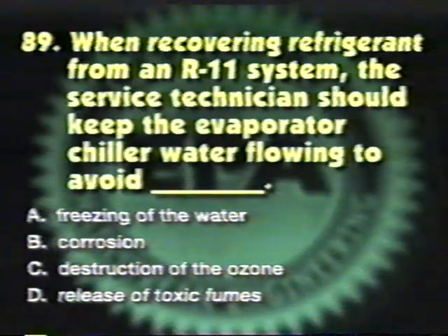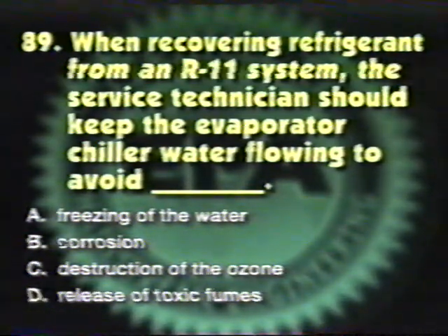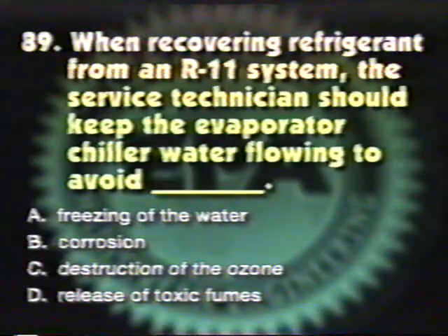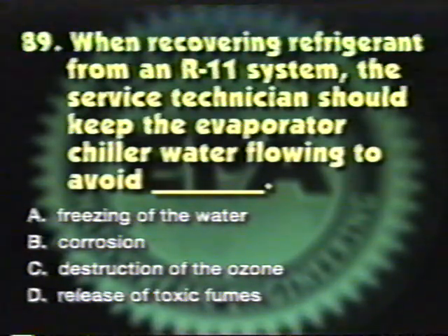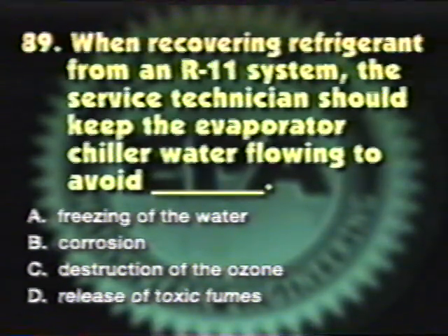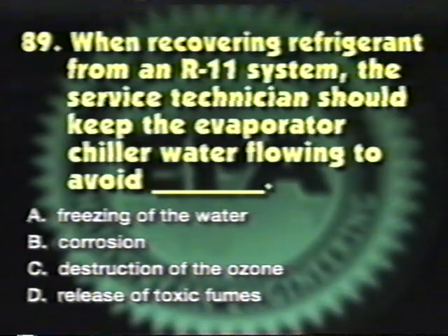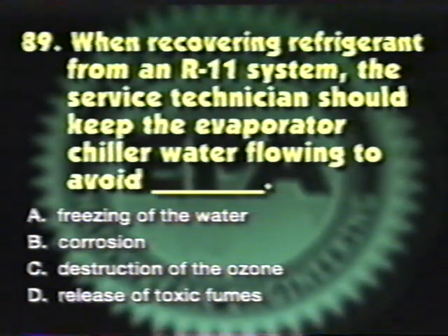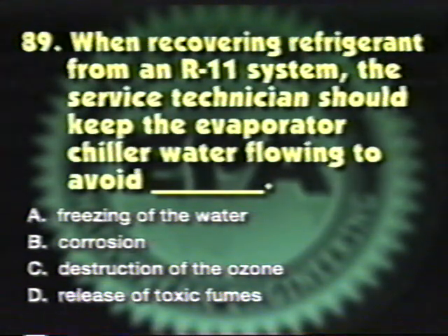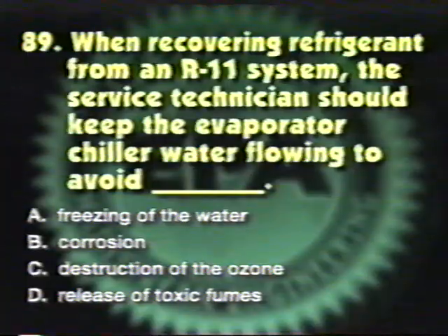When recovering refrigerant from an R11 system, the service technician should keep the evaporator chiller water flowing to avoid: A. Freezing of the water, B. Corrosion, C. Destruction of the ozone, D. Release of toxic fumes.